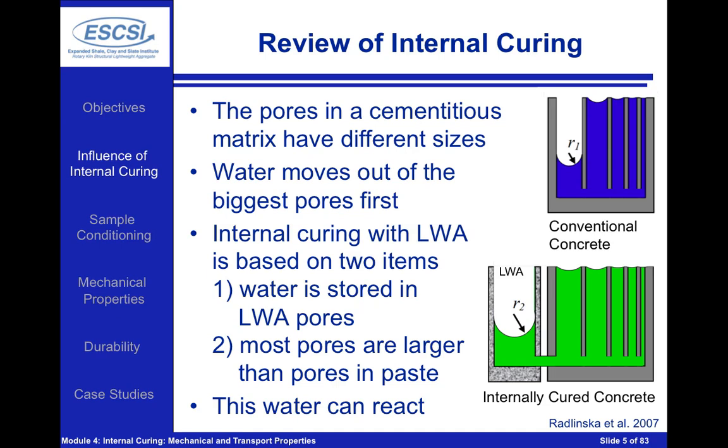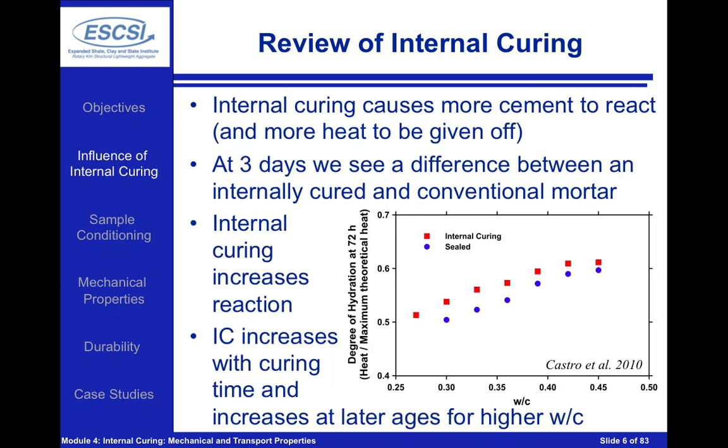Internal curing using lightweight aggregate is based on the principle that water is going to be stored in the pores of the lightweight aggregate, and those pores are larger than the pores in the paste. So if we look at the diagram toward the bottom here, the whole concept is that water will leave the lightweight aggregate and fill in the pores in the paste. This water will then be available to react with the cementitious material and can hydrate the system further. And this is exactly what we're after. We're after the water moving from the lightweight aggregate into the paste to sustain the hydration reaction.